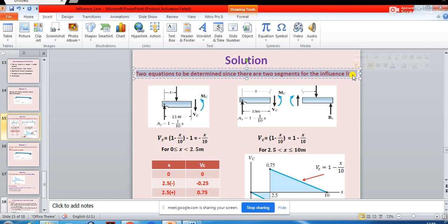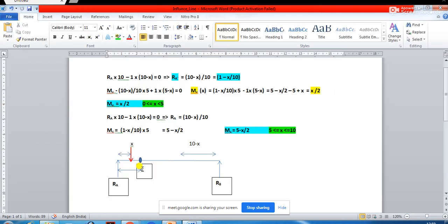Do you understand? Okay. So next, if you want to find out the shear force, then what is shear force? Shear force is nothing but whatever reaction is acting and whatever loads are acting, you will have to add or subtract them. Upward direction things you will have to put some sign, and downward direction things you will have to put some sign, and then subtract or add, depending on the direction of load.